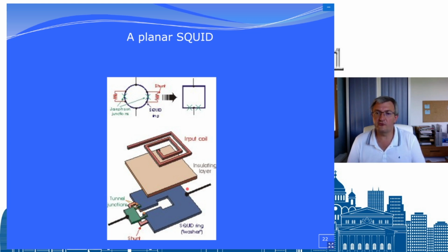So you have a flux transformer, like you can have a voltage transformer in AC electricity, and it's a way to do, let's say, a flux impedance match between the device, which is here, the two junctions, and the external magnetic field. So all kinds of techniques to develop a good squid. It's really a work of specialists.